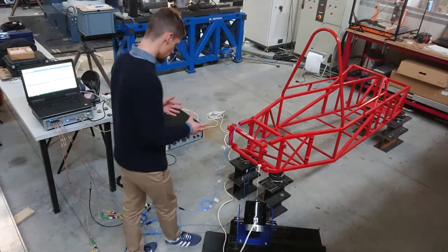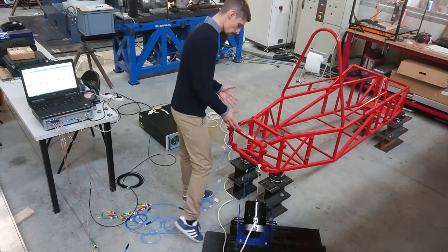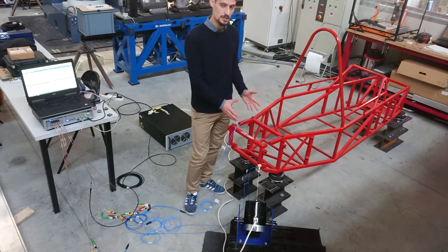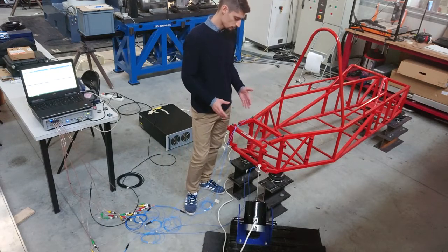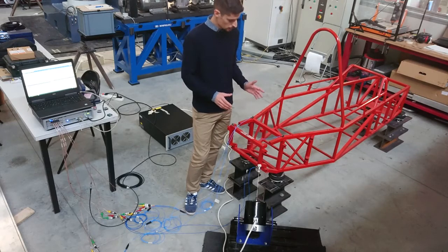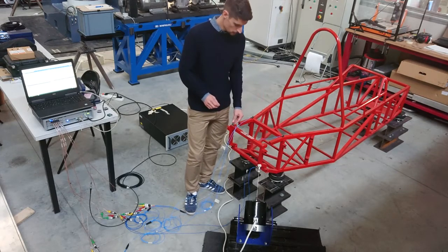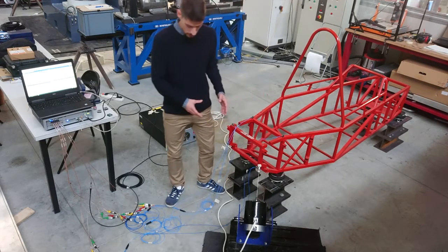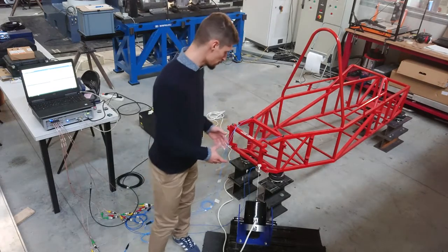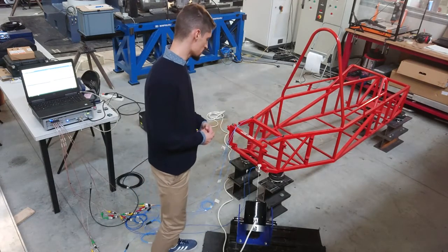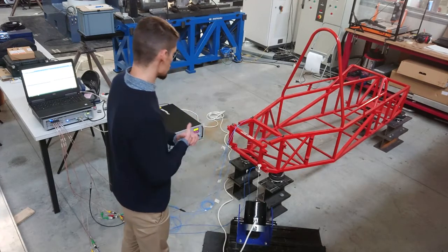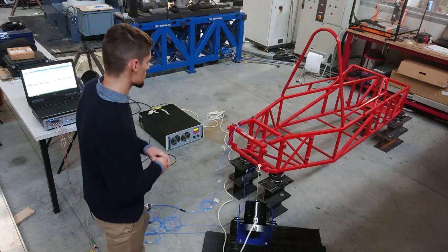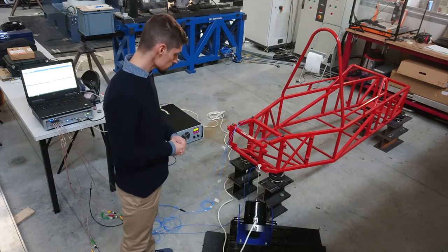Let's try to imagine that you have a local mode in your structure, I mean a mode that concerns just a specific area of your structure, and for any reason at the beginning you didn't consider a measuring point near this area. You cannot catch this local mode and you probably make a mistake. So in this case I have done the work for you. I divided the structure in 22 points.